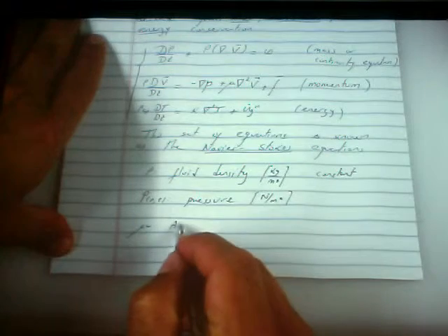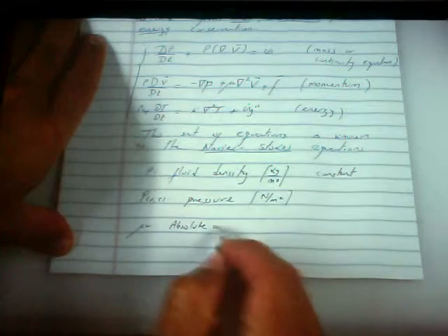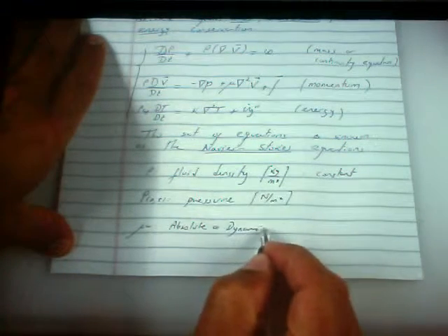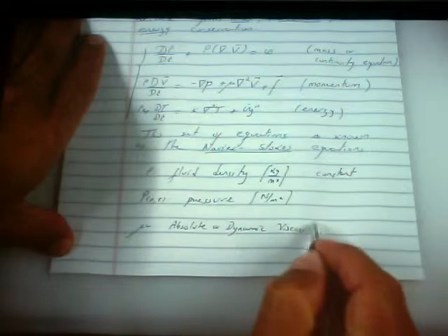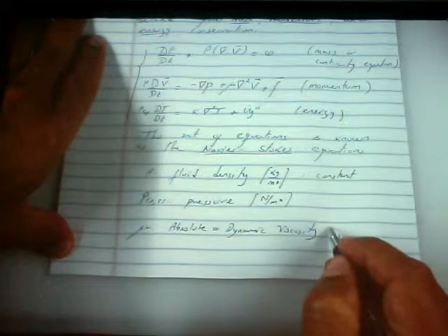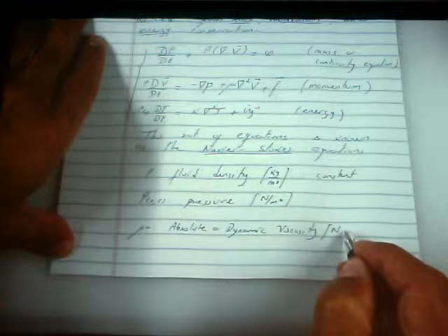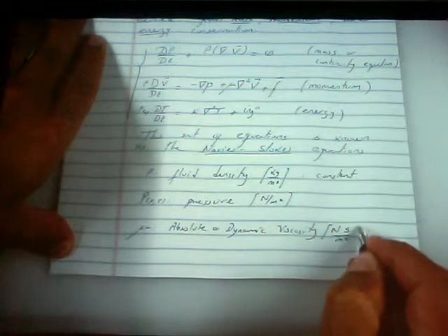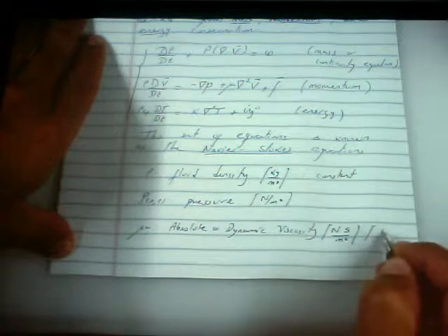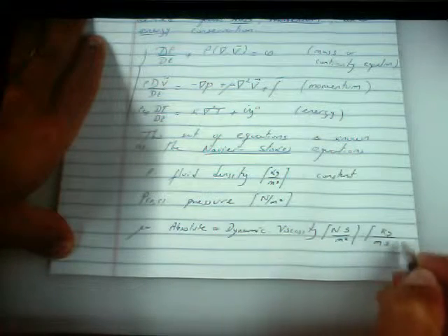That's the absolute or dynamic viscosity. And that is in newton seconds over meter squared, or the same thing as kilograms per meter second.